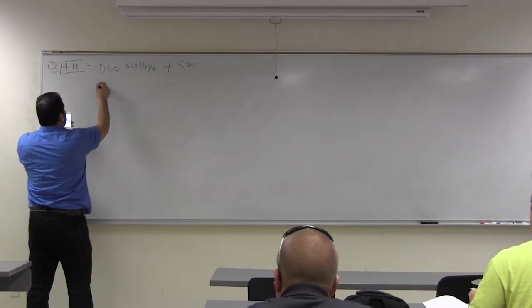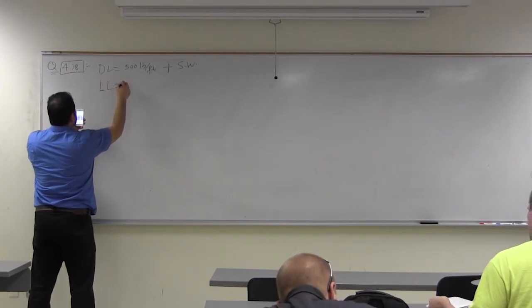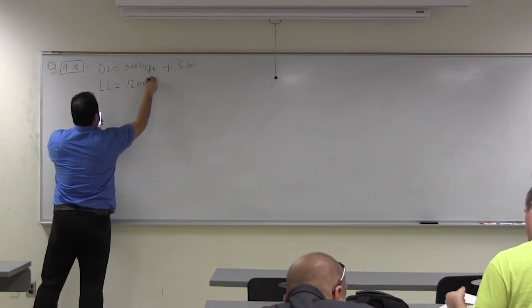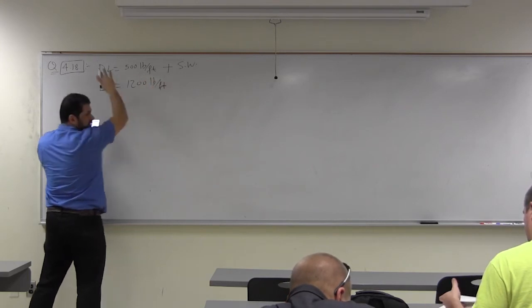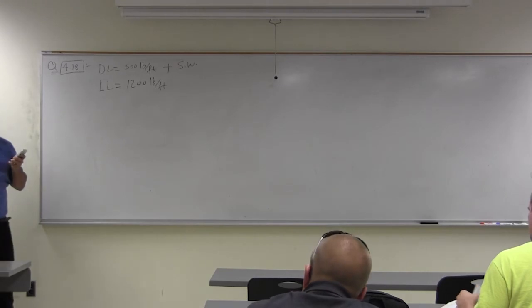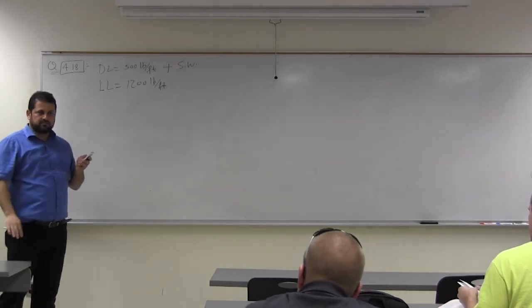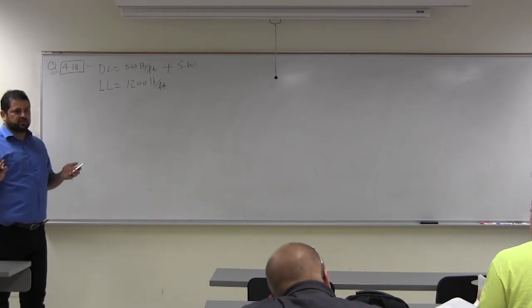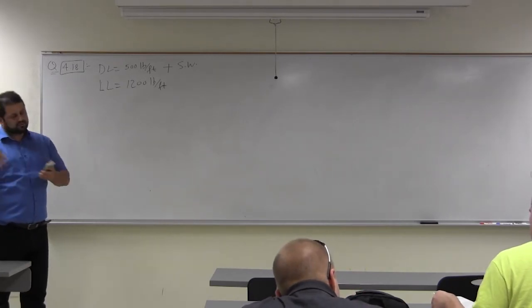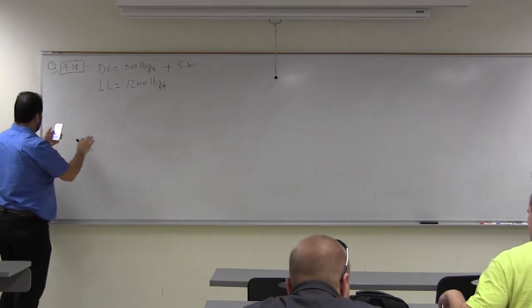And live load equal 1200 pounds per foot. These loads are service loads. Anytime he gives you a load, if he doesn't say the word ultimate loads, they are service loads. If he doesn't say the word factored, they are service loads.